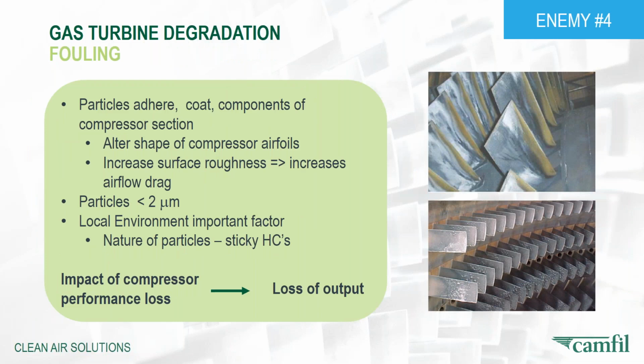Our fourth enemy today is fouling of the compressor section. And this is the case where, as opposed to erosion, where we're taking material away, we're actually adding material to the compressor section. Small particulate are adhering to the components over time and slowly building up.